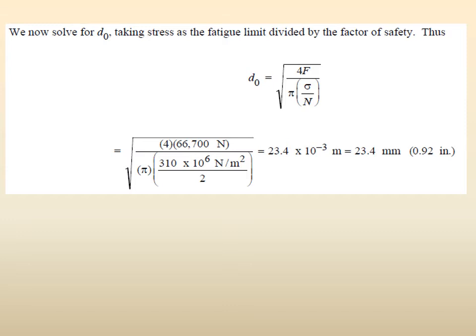We have done one example where we calculated the basic things, amplitude and stress range and so on. And here, if an S-N graph, or stress amplitude versus N graph, is given for different materials, we did it for an endurance limit material where failure will not occur. Otherwise, on the same graph, we could say that this is the fatigue strength that we mean.